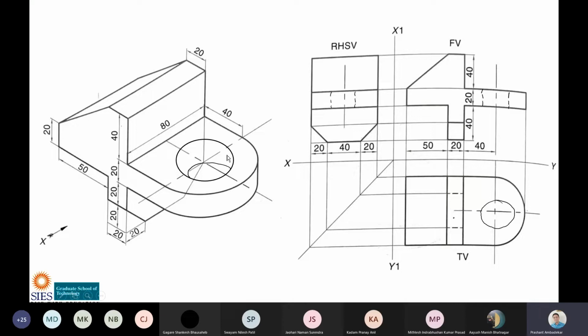So whenever anything is added, it has to be reflected in all three views. See, now this circle from the top view is drawn here. Some of you must be thinking there are two circles. No, it's not like that. It is the same circle. You can see this is the hollow part where my cursor is. The width of the circle is seen because it is inclined. So there is nothing here. This is the bottom portion of the circle, the lower portion where the circular hole is cut, that is visible. So this circle is drawn in this view.